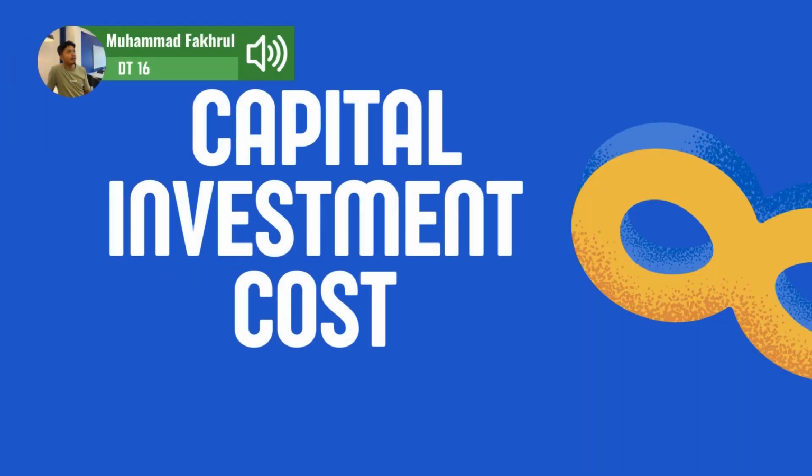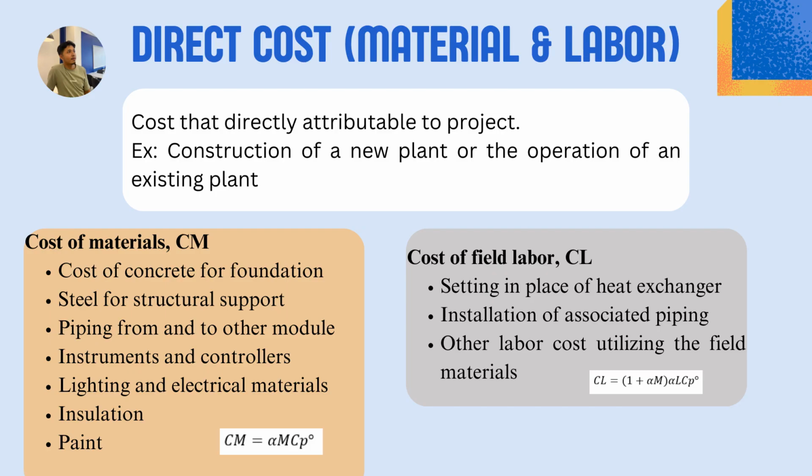So next we move to capital investment cost. In capital investment cost, we have direct and indirect costs. For direct costs, we have material and labor. For cost of material, such as cost of concrete for foundation, steel for structural support, piping from and to other modules, instruments and controllers, lighting and electrical materials, insulation and paint, the formula is Cm equals alpha MC times Cp.